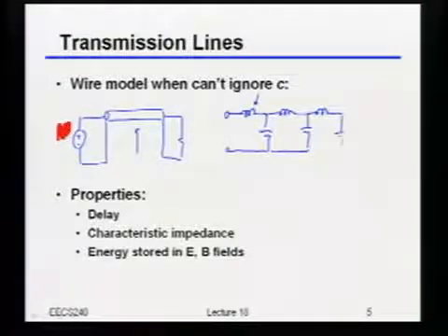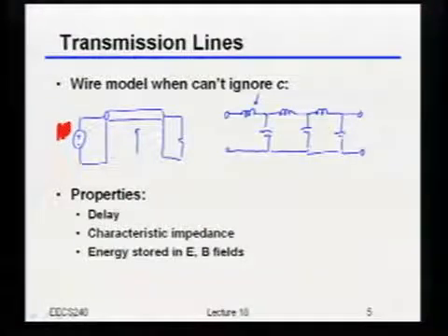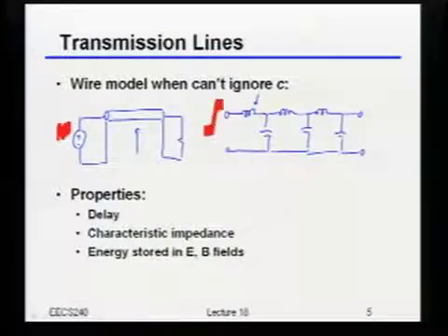So essentially, we can model our transmission line as this distributed LC network like this, okay? So clearly, we're going to store energy in this. You can quickly figure out that there's going to be delay in this thing because, you put some, let's say, voltage step right there. Well, the inductor has to charge up, then it'll charge up the capacitor, then this one has to charge, and so on and so forth, right?